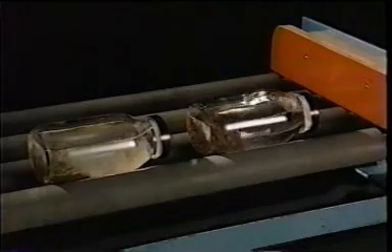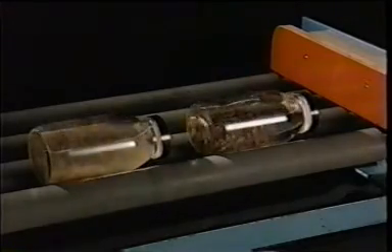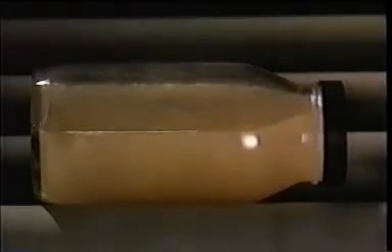How the drilling fluid interacts with the rock that's being drilled is also an essential element of the hole cleaning system. If we are drilling with a dispersive system, where the drilling fluid can penetrate the cutting and dissolve it into solution, then most of the hole cleaning is accomplished through this mechanism. However, if the drilling fluid is fully inhibitive, such as this clear base oil, then the entire cutting must be removed from the hole mechanically.